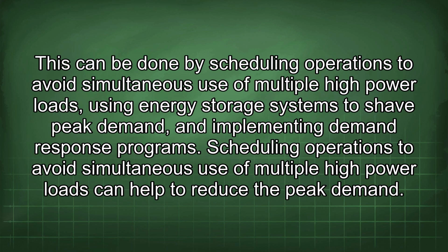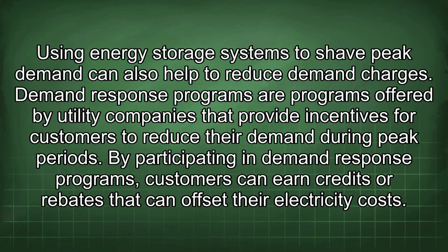This can be done by scheduling operations to avoid simultaneous use of multiple high-power loads, using energy storage systems to shave peak demand, and implementing demand response programs. Scheduling operations to avoid simultaneous use of multiple high-power loads can help to reduce the peak demand. Using energy storage systems to shave peak demand can also help to reduce demand charges.